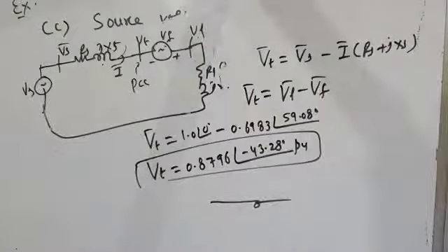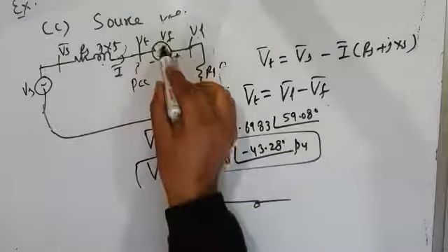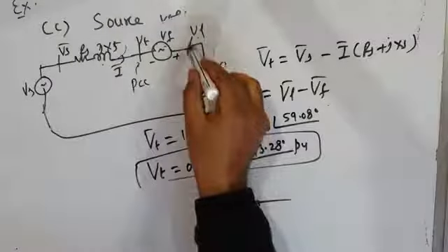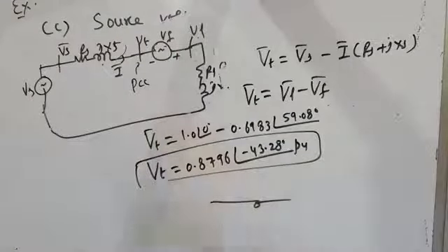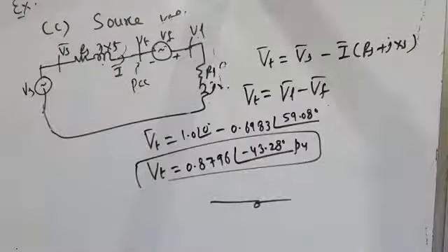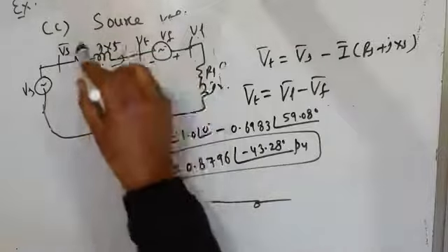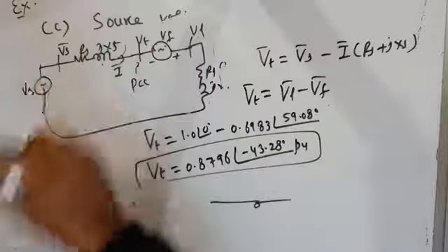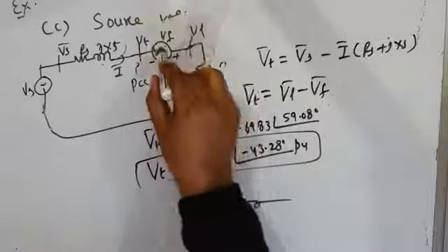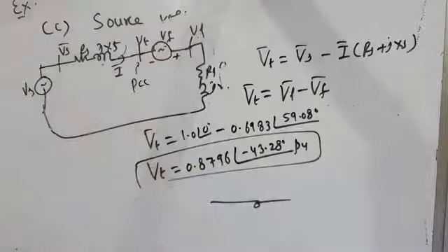It synthesizes the voltage source, it injects the compensation voltage, or the filter voltage VF, in series with the load in order to regulate the load voltage. Right now we are only studying load voltage regulation, making load voltage the same as source voltage, so that the voltage drop which was making load voltage less than source voltage is compensated, and this DVR compensation voltage makes load voltage exactly equal to source voltage. We have been discussing this function of DVR.